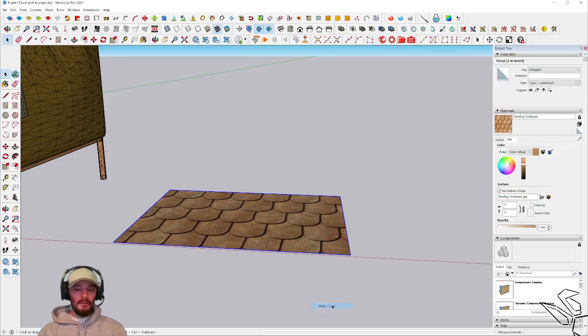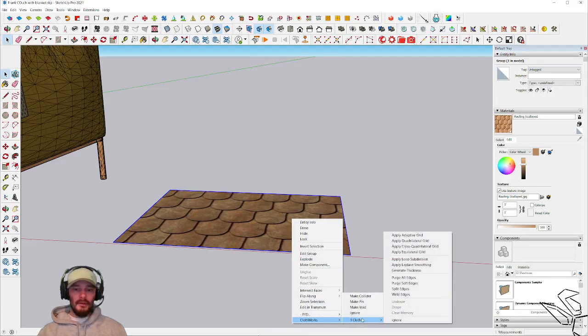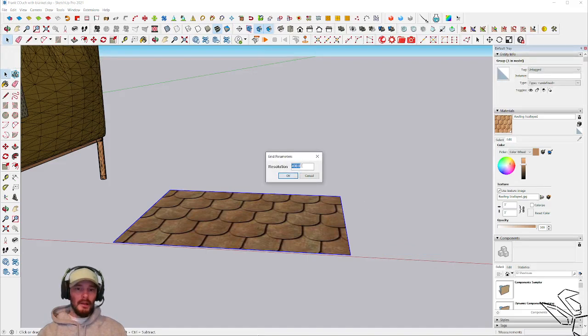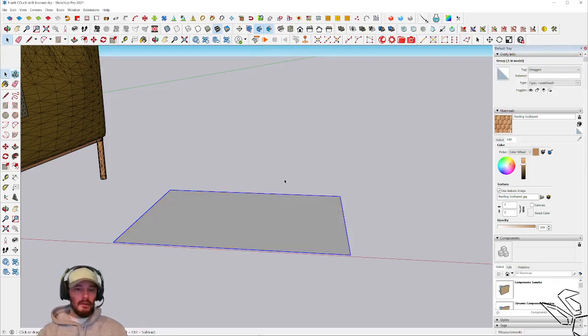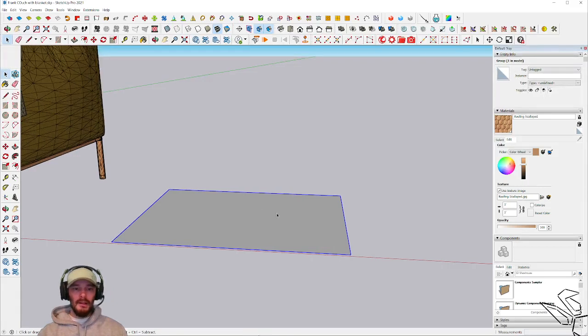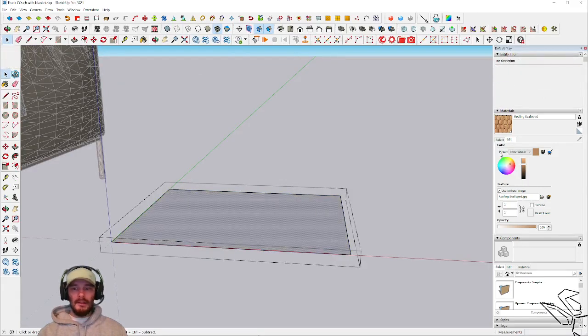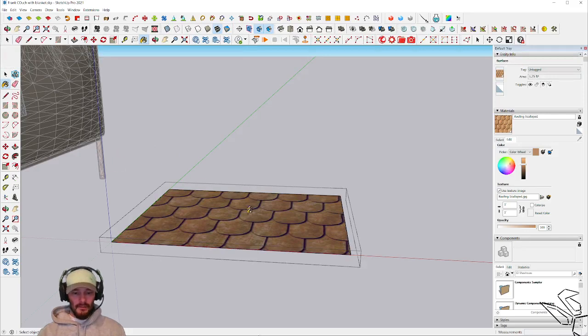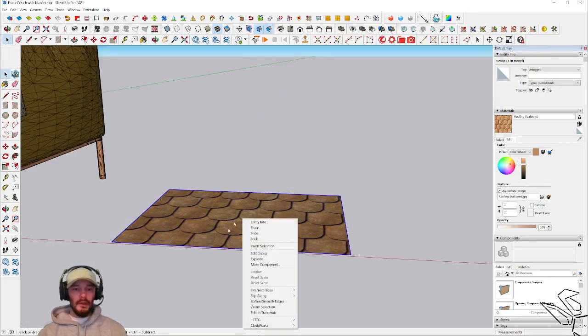ClothWorks, I'm going to make it a cloth. There we go. I right clicked, make it a cloth. Now that I have this as a cloth, I have an option here. I'm going to apply an equilateral grid and put a resolution to it. 24,500 is good. That's kind of an arbitrary number until you really get to know the software. And it's good to just make sure that this is reapplied because sometimes when you're applying a new mesh geometry to an item and it's committing to it, you lose the texture. So here we go. We've still got our cloth.